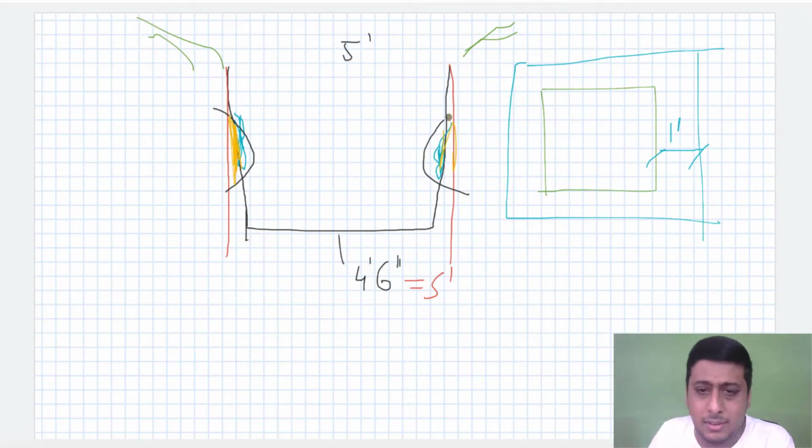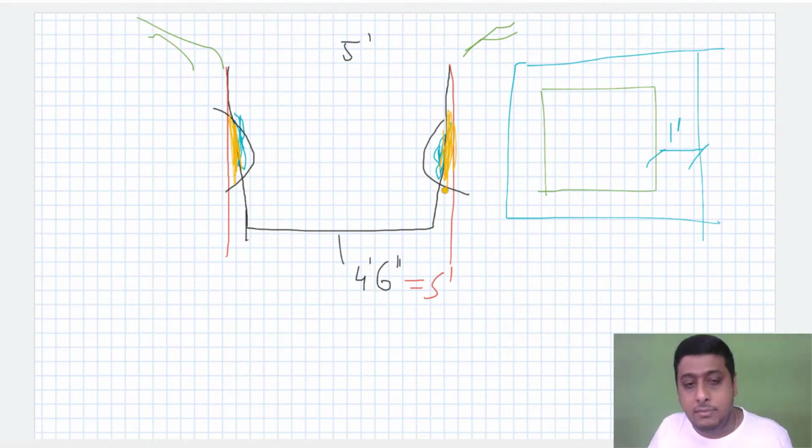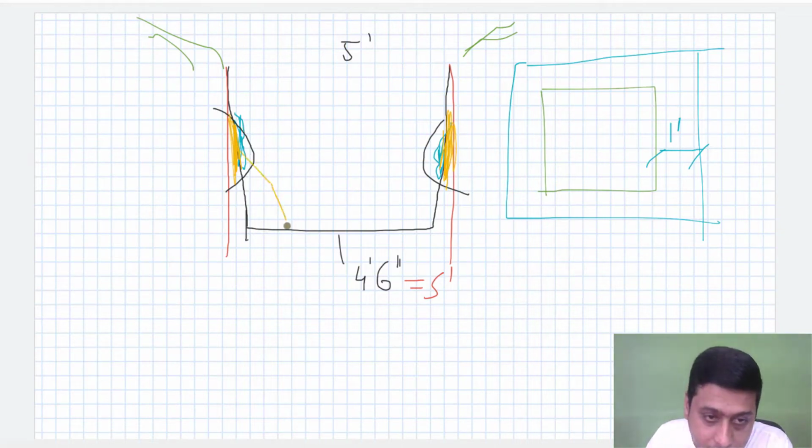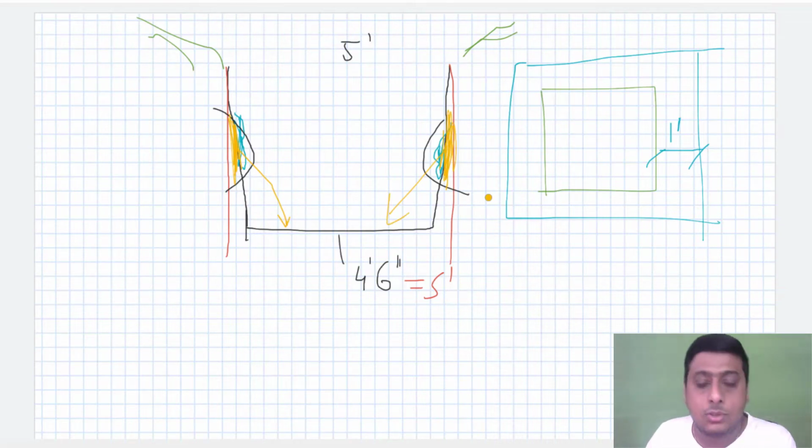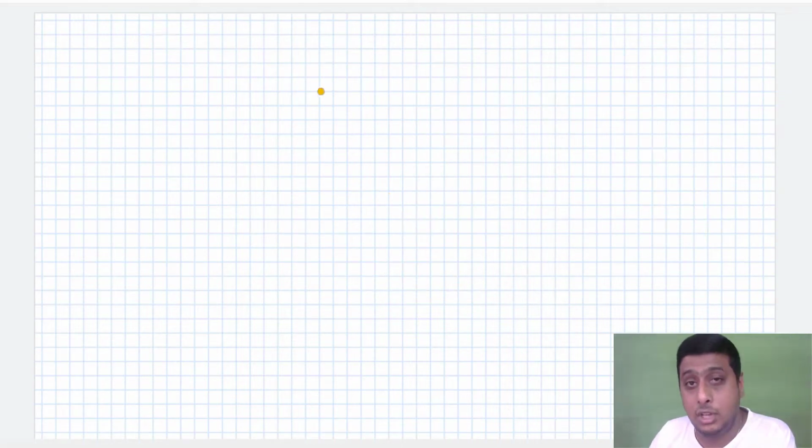It need not be a strong mortar. When you actually start the work there, the particles may be scooped because of the vibration of the mixer or anything, and may fall into the pit again. These are some of the things we have to see as a site engineer when we are actually practicing.